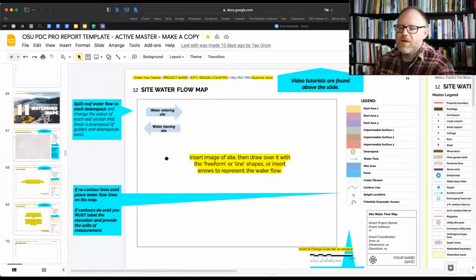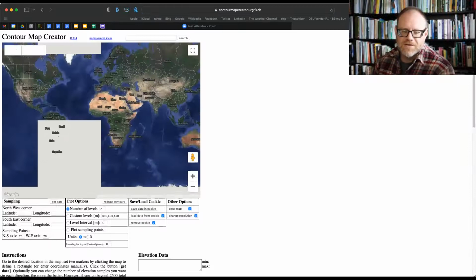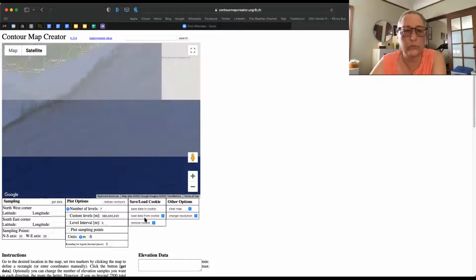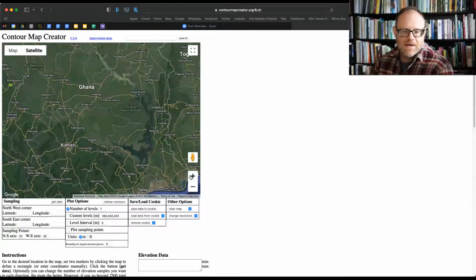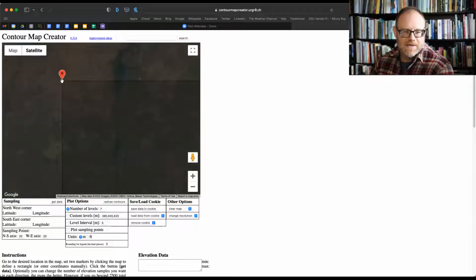So there's something called the contour map generator. There was another company that took the name and created their own for a paid version, but it's the exact same data. So contour map generator here. Here we can zoom in and use an area of interest. So we can come in here to Guyana, and we can create a little area of interest by just drawing two squares here.